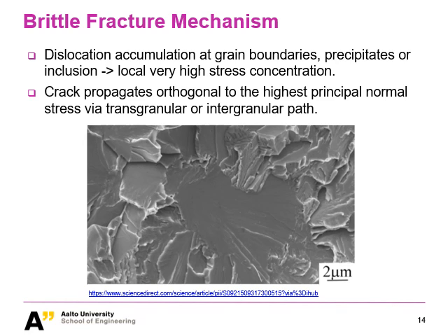And here I'm showing you one typical scanning electron microscope (SEM) figure of a brittle fracture surface. As you probably remember from the tensile test, it's purely flat, but we already have some proof, at lower resolution, that the crack is probably not that flat.